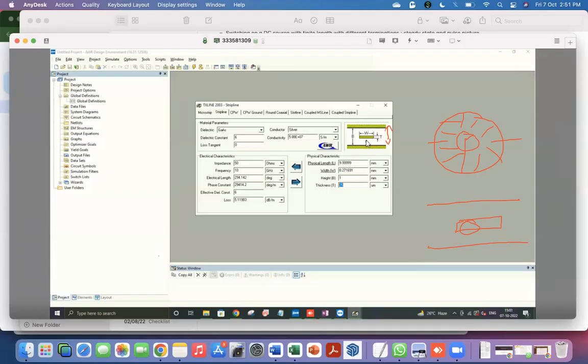Okay. But between microstrip and strip line, this difference that the field lines are entirely inside the dielectric and only one type of dielectric for the strip line, versus the fact that the microstrip line has field lines in air, actually changes the nature of the transmission line itself, in the sense that the modes which are propagating on microstrip are called quasi-TEM.